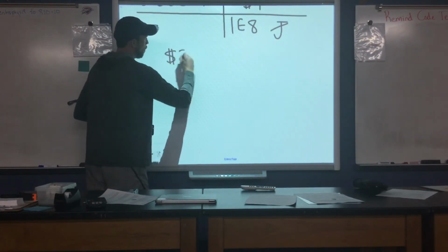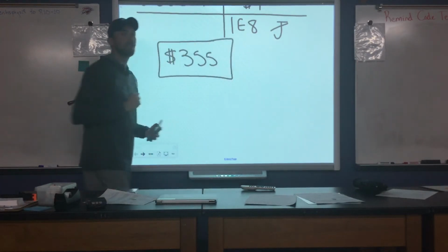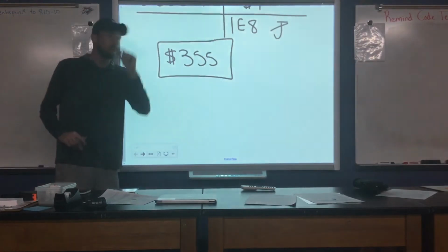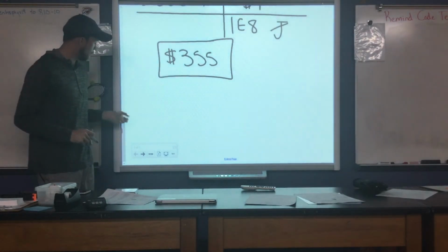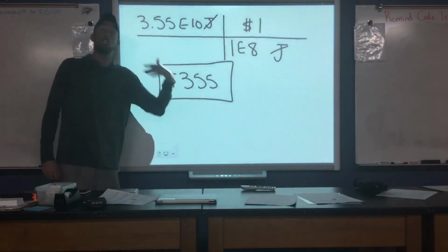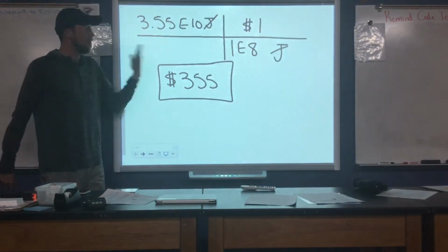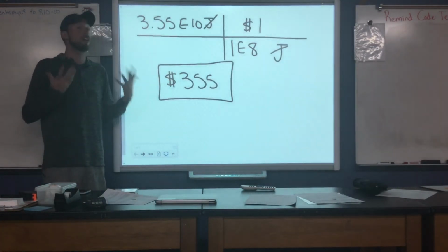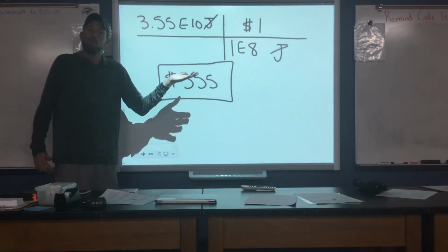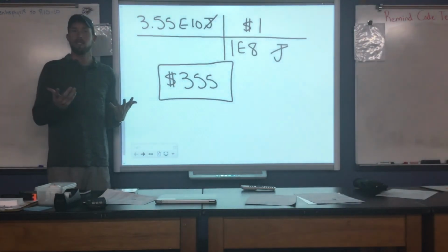So that would tell me that based on the dimensions of the windows I have, based on the material those windows are made out of, the glass, based on the thickness of our window, as well as the inside and outside temperatures, I would be spending about $355 per month on the energy lost through all 10 windows. Now, if you know anything about a heating bill, you'll know that's a pretty high value. That's a lot of money to be spending. And so you might think, well, is that number realistic? Is it wrong? Well, no, not necessarily, but we need to put that number in context.